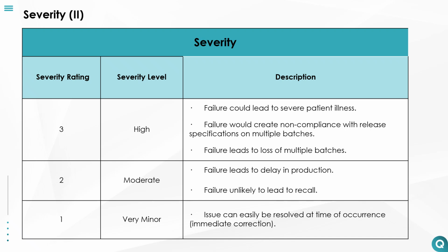For example, a severity rating of 3 would include something like a failure in a sterile filtration system of an injectable drug production line, which results in microbial contamination of the final product. This contamination was only discovered after distribution, leading to several infections or fatalities amongst patients. This necessitates a product recall, halting production indefinitely, and triggers extensive regulatory investigation and legal actions. The impacts on patients' health and safety, along with operational financial repercussions, justify a severity rating of 3.